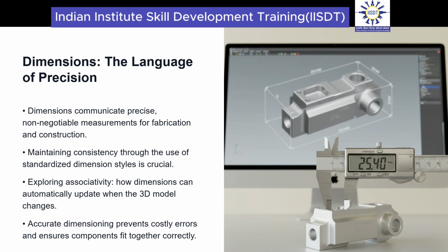However, simply placing numbers on a drawing is not enough. Consistency is paramount. Through standardized dimension styles, we ensure that every measurement across a multi-sheet drawing set is presented with the same text height, arrow style, and precision, making the documents easy to read and interpret.